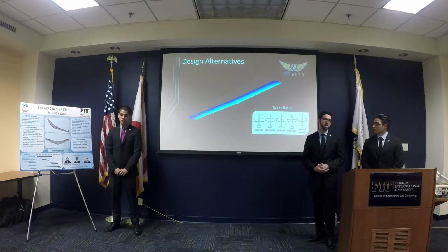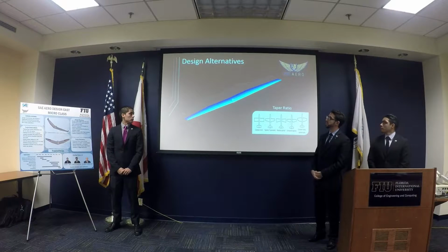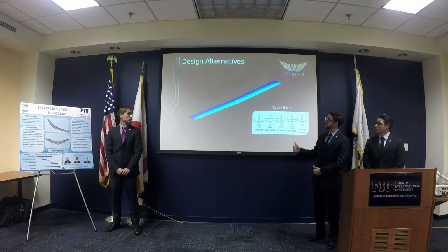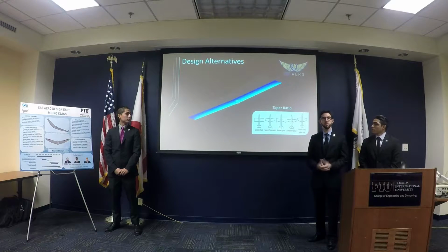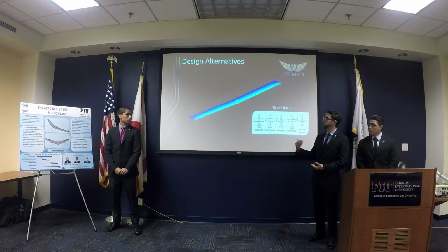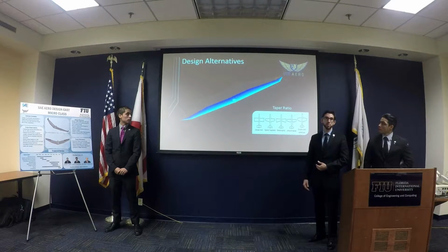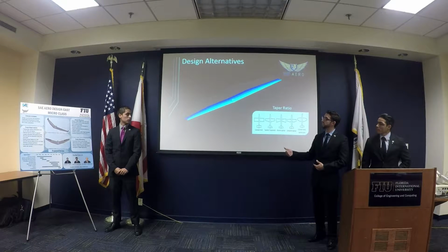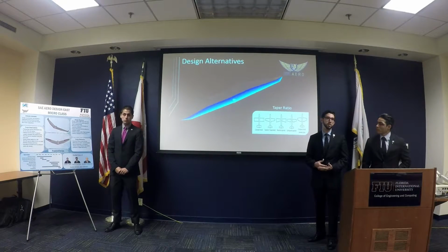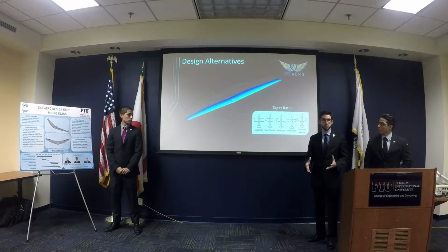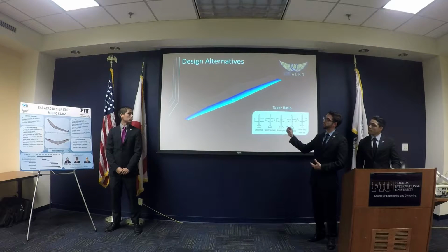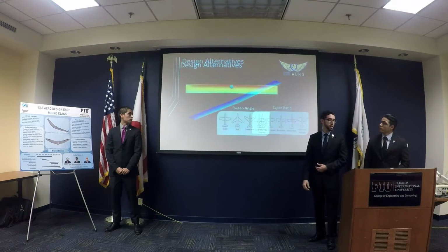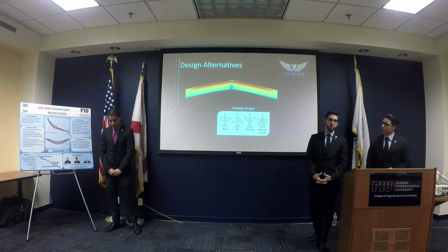This slide is an illustration of what happens when you use another performance improving method, which is taper ratio. On the first picture you can see a very large induced drag plot. It's not really numerical, it's more a graphical representation of what will happen as you increase the taper ratio. The closer it is to 0.5, the less induced drag you experience, and on the last snapshot you can see what are called raked wingtips. These are used on very cutting-edge plane designs nowadays, and as you can see, it basically cuts down the induced drag.